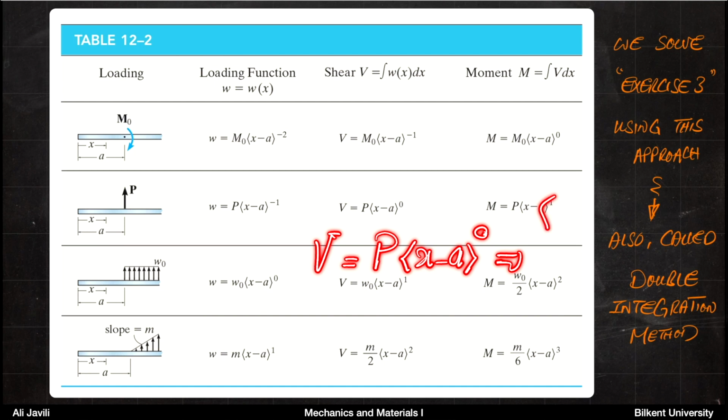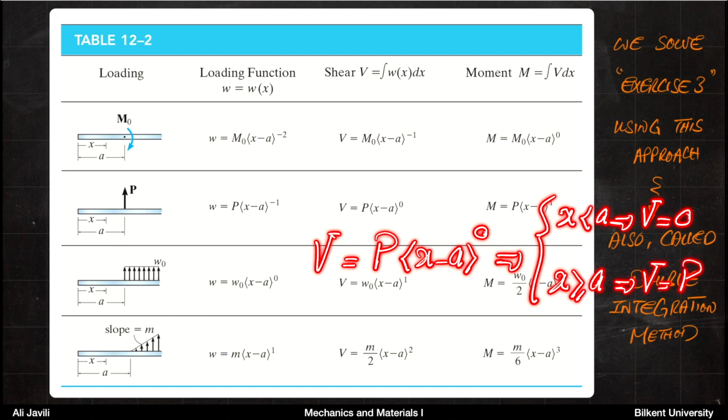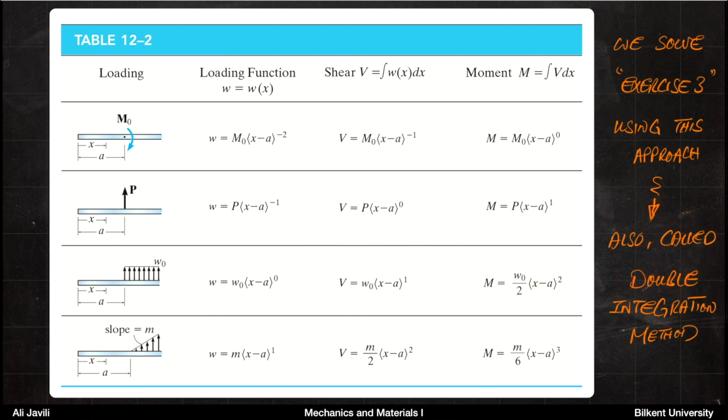Now, again, that means if x is less than a, you just get a shear force of 0. And if x is greater than or equal to a, you get a shear force equal to P, which is exactly what we wanted.